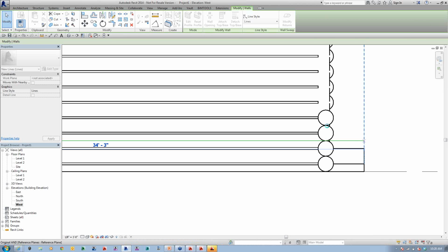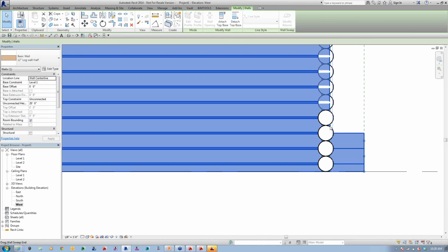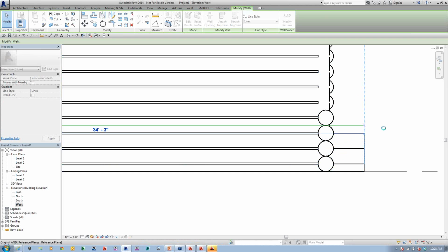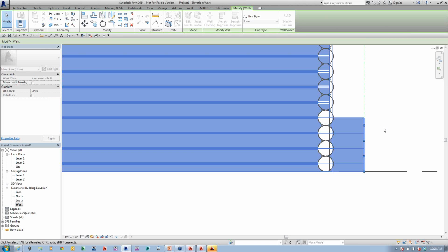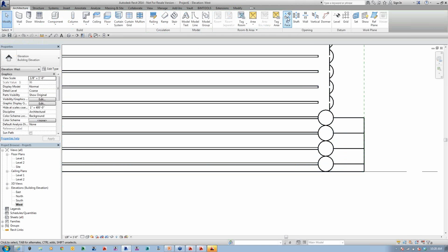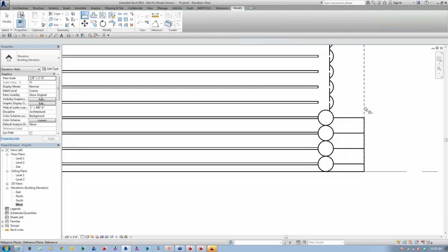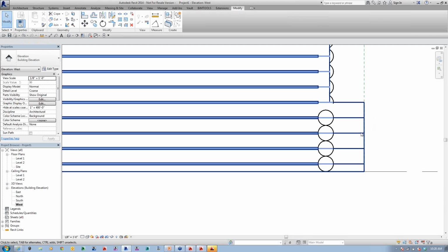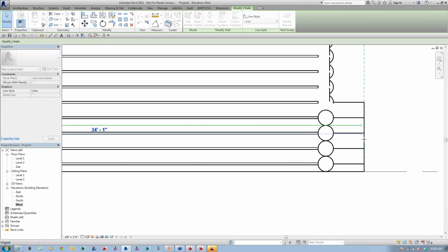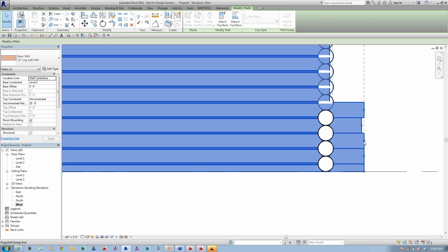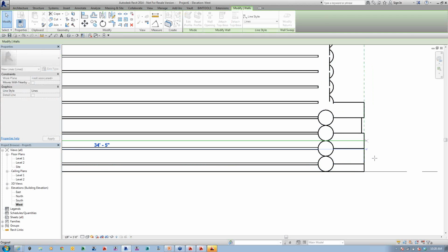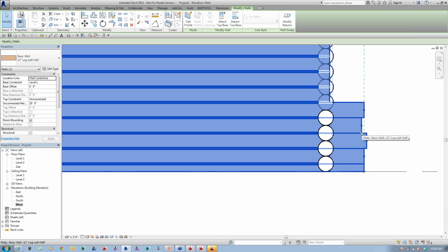And just as a note, Brian, Kyle makes the comment that he's also used the align tool and aligned to the faces, so that's another method of potentially doing this. I guess sometimes I like doing the log wall this way, because I'll vary it a little bit from side to side. So I guess that's why I'm more used to doing it this way, because then I'll get, well, that log's a little bit out, that log's a little bit shy, and then it looks more authentic, so I get this little stagger look in here.